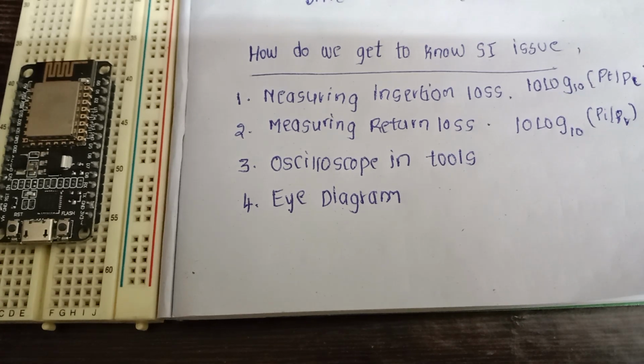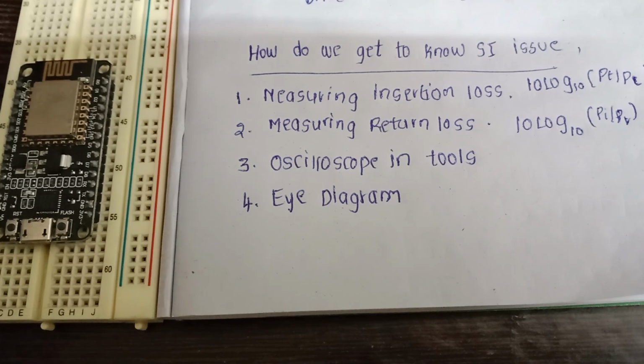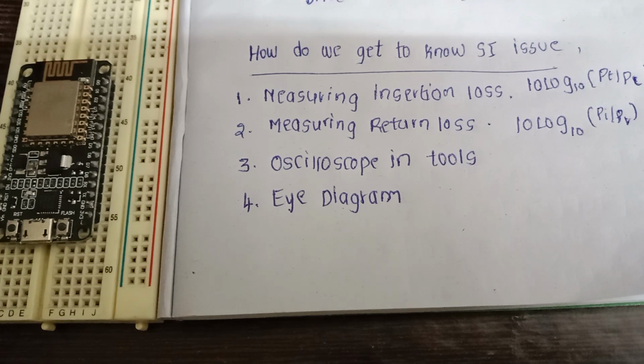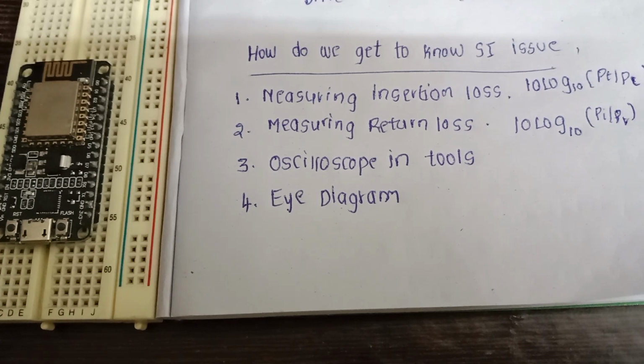By this eye diagram, which is formed by taking a number of samples of the signal, we can get to know what is the jitter that is there in the channel. And we can also have the exact parameters which are required, which will fail. For example, if you have a lower threshold, upper threshold, the rise times, the fall times, all these can be used to form something called an eye mask, and then we can see the signal performance using that eye diagram.